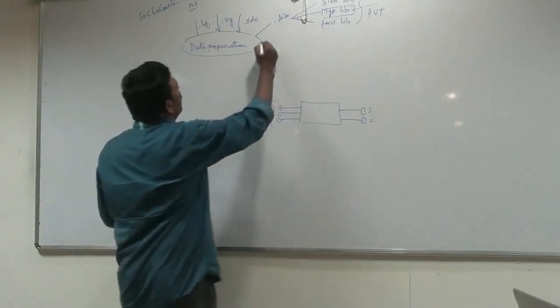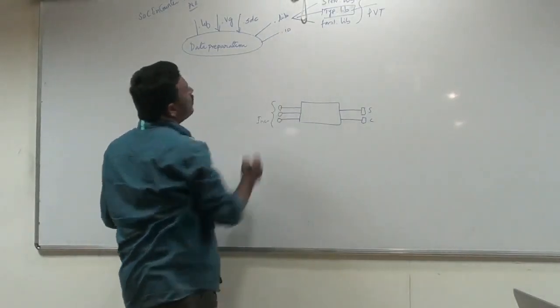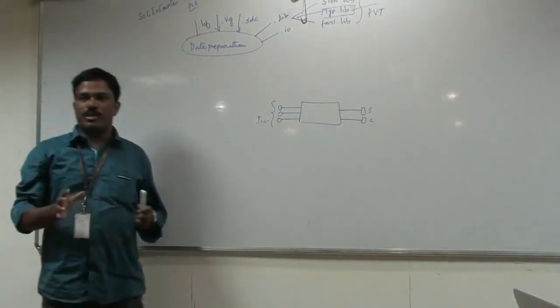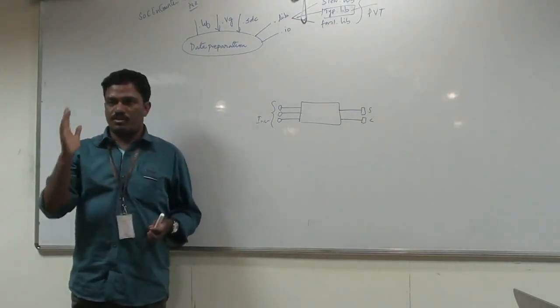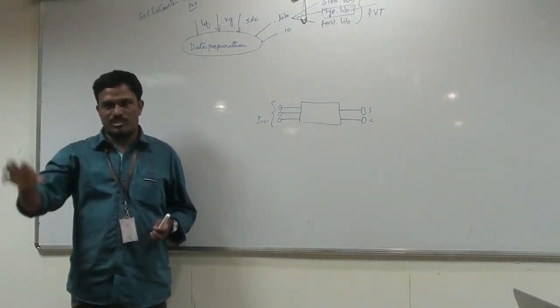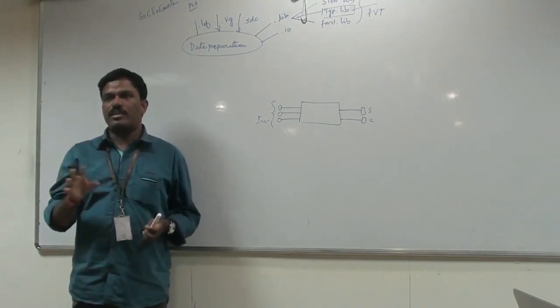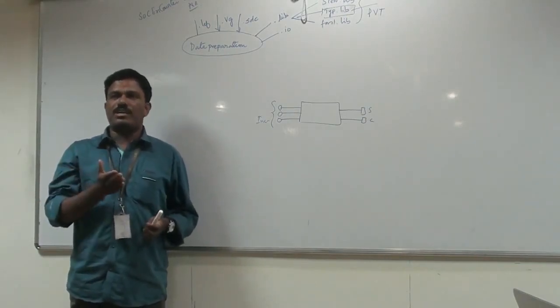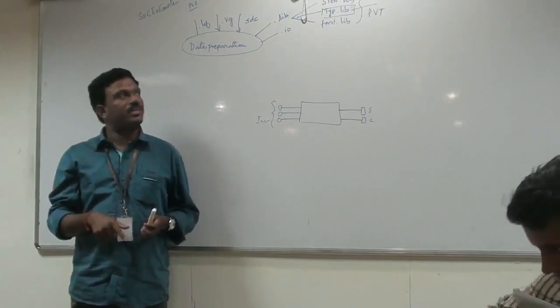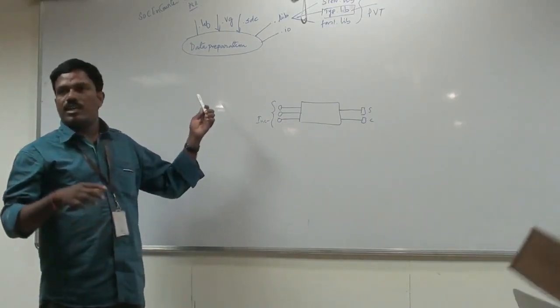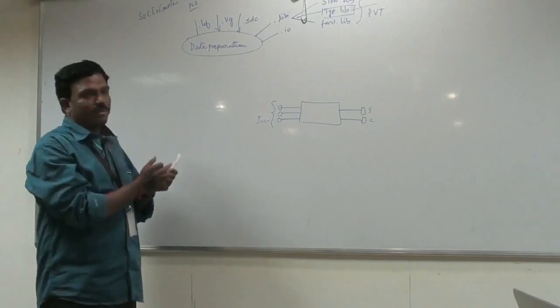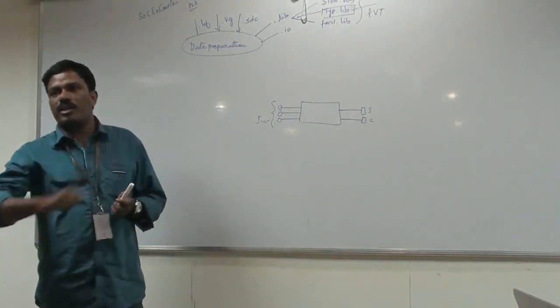So that IO file is also required for us. That is also another input for the backend. So we need the input output file, that is the inouts of your design, the SDC, constraints related to the design, the gate level optimized Verilog netlist, then the LEF, right? This is the minimum requirement we need before entering into the backend.